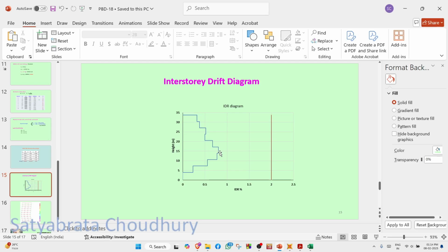So in the direct displacement based design, the method is not telling you anything regarding the choice of the initial member sizes. So you have to make many iterations so that you arrive at the correct size, and then perhaps the drift diagram may be coming near to this target 2% drift. I have tried only one time history here. You have to actually use around 11 time histories.